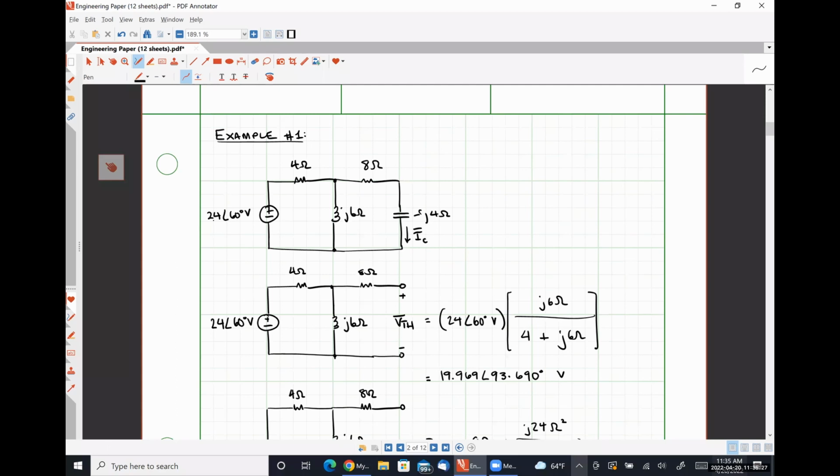One thing that we could potentially do here would be to apply nodal analysis. You may be asking yourself, well, why can you apply nodal analysis, which is setting up a system of equations, and not mesh analysis? And the short answer here is that the nodal analysis isn't really nodal analysis. It's more applying Kirchhoff's current law at our top middle node.